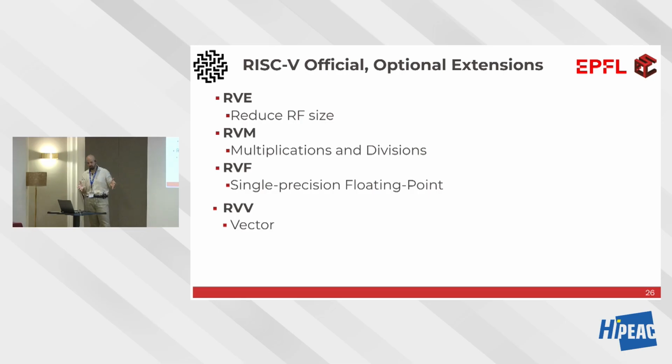So, I know you guys know the answer, but is code compiled with a custom compiler with custom extensions able to run on every other CPU based on RISC-V? No, of course. It's not the case for standard ISAs, and it's even less the case for custom ISAs, because maybe I don't even give you the spec. I can implement them and keep them closed source, while these guys are open source.